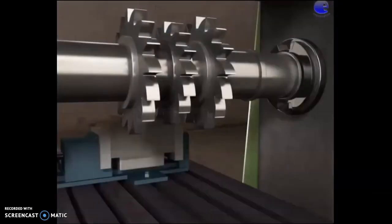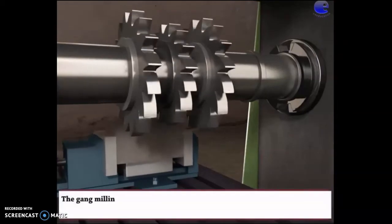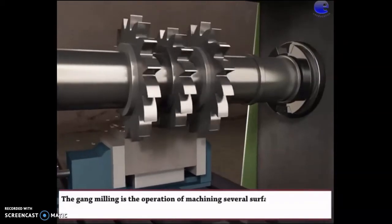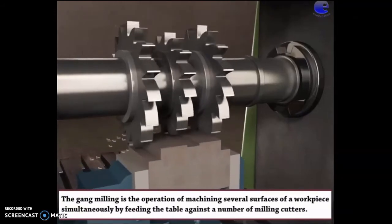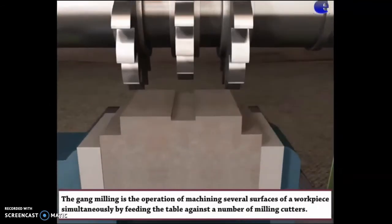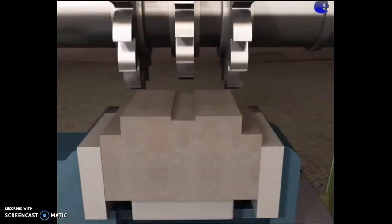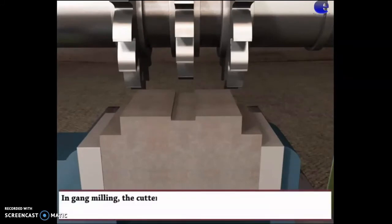Next is gang milling. Here is the arbor, side milling cutters. Gang milling is the operation of machining several surfaces of the workpiece simultaneously by feeding the table against a number of milling cutters, as you can see in the animation. This method saves much machining time. In gang milling, the cutter speed is calculated from the cutter of largest diameter.